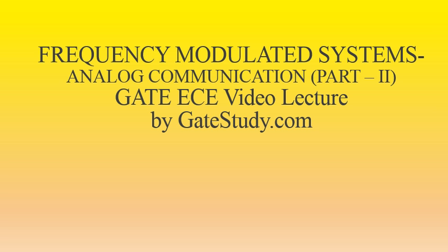Bandwidth in frequency modulated systems is estimated using Carson's rule, that is, bandwidth is the sum of twice the peak frequency deviation plus twice the message bandwidth. Wideband frequency modulated signals can be generated by narrowband FM signals and frequency multiplication or by direct methods. Demodulation can be done by using a discriminator or by a phase lock loop.